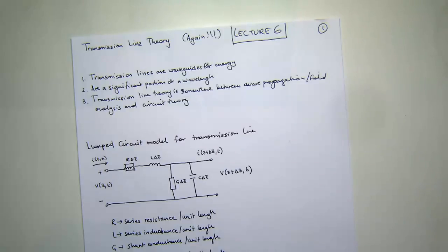Right? So even though you flick the switch in the DC, unless it's perfectly matched, you do get these transients. The line's charging up, and that disturbance travels across the line. If the impedance isn't matched, and we'll do all these bounce diagrams in two lectures' time, you get a reflection, it comes back, hits your generator, and goes back, hits the source again. So you get this fluctuation in your voltage across that transmission line.